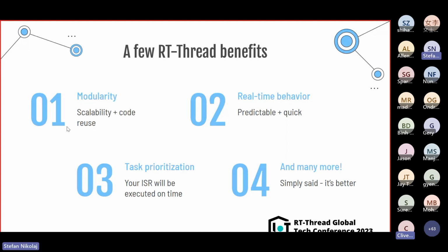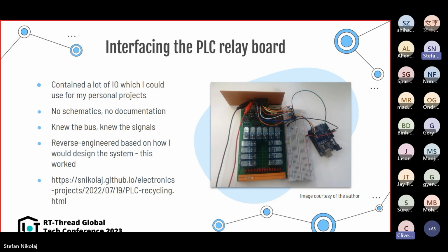And finally, I want to talk a bit about interfacing the PLC relay board. So this is an older image using an Arduino, but what I want to show here is how my prior knowledge of the system's architecture and the use of a Z80 processor enabled me to identify the presence of a multiplexed Z80 bus.